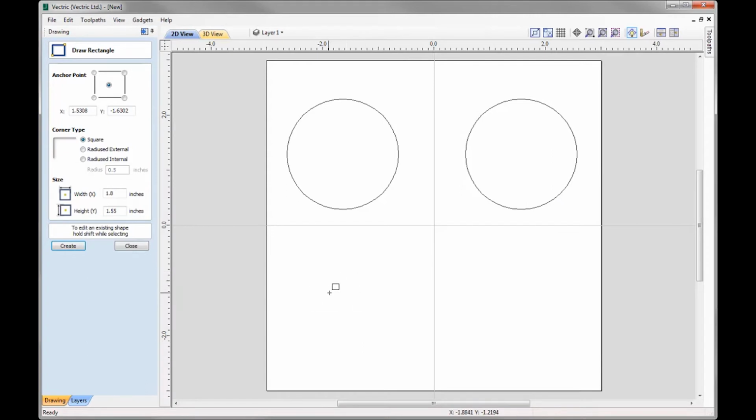So to draw a rectangle, we simply begin drawing the rectangle with our cursor, and then we type in values that apply to the width and then to the height. So the first value is the width. For example, I want to have a width of 1, so you'll see highlighted at the bottom, I'm going to type in the value of 1 for the width, comma, 1 for the height, and I'm going to press return, and that will create a square that is 1 by 1.